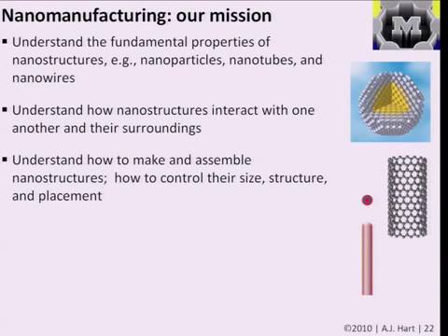So now we can say, well, I know that I want a silicon nanowire of 2 nanometers diameter because it has property A that's useful for my solar cell. Well, how am I going to make it so I have 2 plus or minus 0.2 nanometers diameter and have that really good process control? That's difficult, and there's still a lot of work to be done in those kinds of areas, but we're starting to see and can in fact relate some concepts from basic chemical kinetics and nucleation and growth to the processes that make these structures. And those are the kind of analytical tools and theory that we're going to bring into those sorts of topics.